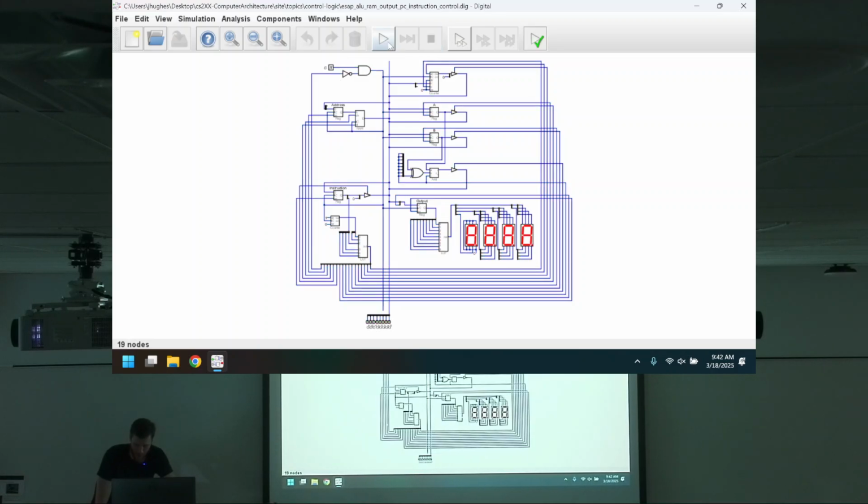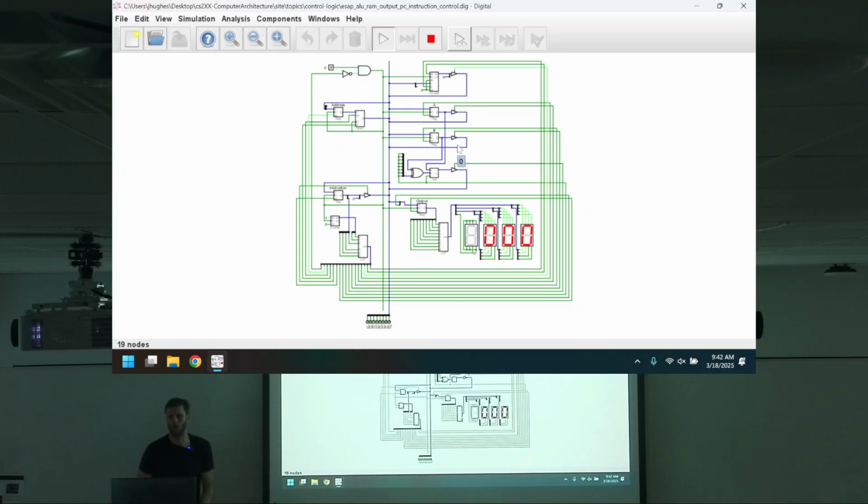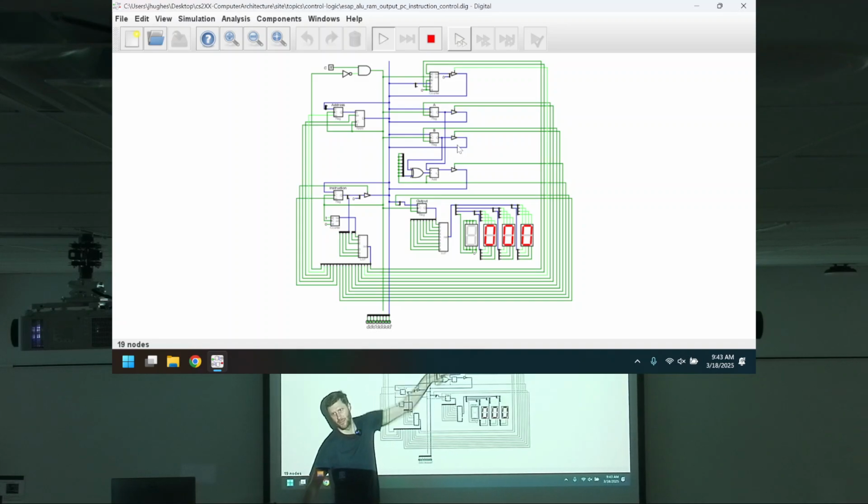Now, by the way, I didn't show you this yet. Remember how I said we have that halt instruction, and we need a way to control whether or not the clock can actually have an effect on the system? That's trivially achieved with a not. I guess a not and an and, right? If halt is on, I want this to be off, and then 0 and whatever clock is 0, so the clock effectively is nothing. If halt is off, that is on and whatever clock is, is whatever clock is. These are those basic Boolean principles.